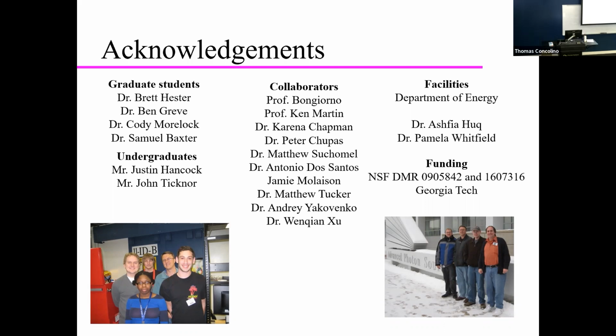And I have some other work that I'm just about to publish where I could show you some data to support that. So I think what's really going on is that this is a way of the zirconium actually achieving its preferred higher coordination numbers. Because if you were cation interstitial, it would all still be 6. And that's probably one of the reasons we add excess fluoride.